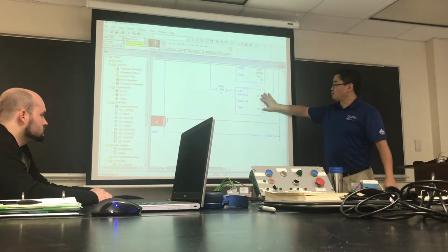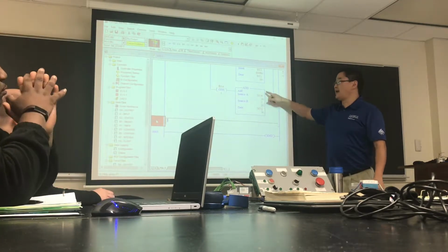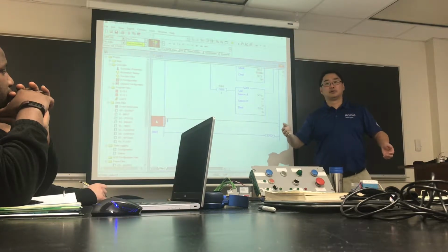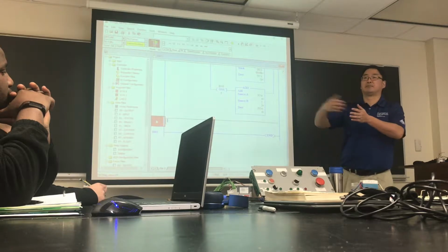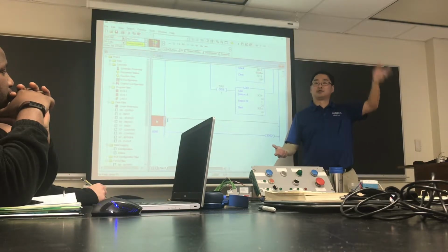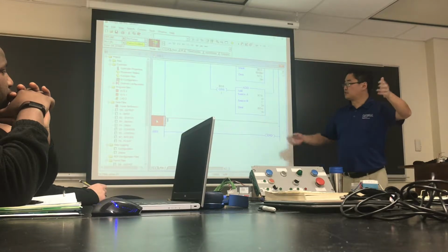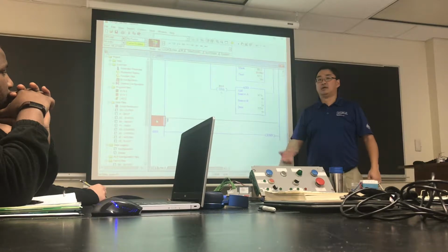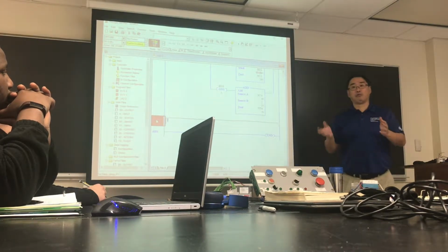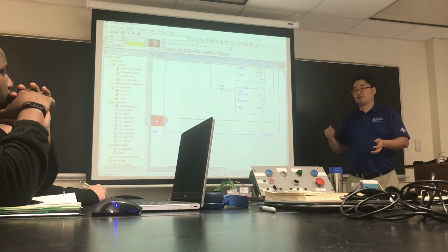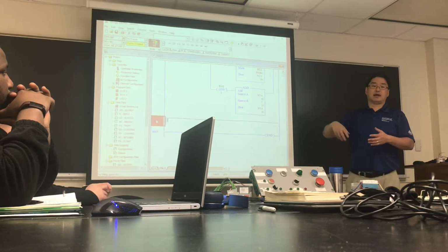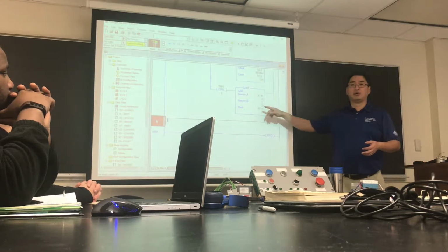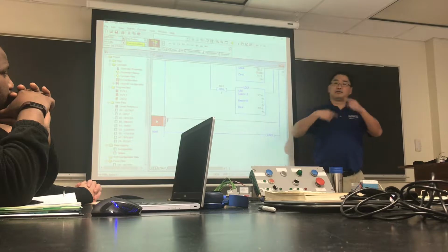Now, if I wasn't referencing myself, if I wasn't saying A equals A plus 1, or 2 in this case, it wouldn't matter, because I just keep doing the same math instruction into the same location. And the answer is the same until one of my sources changes. But sometimes you do have to add back into yourself. Think about doing an average. If I want to do a running average, and every 5 seconds I have new information that I'm putting into my average, if I don't one-shot that add, I suddenly have problems.